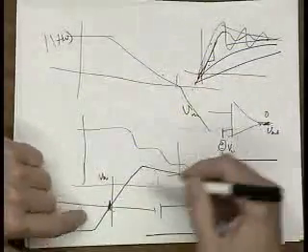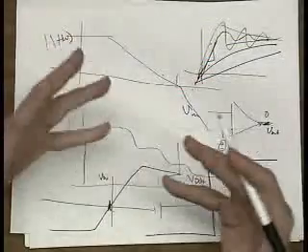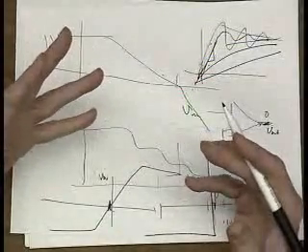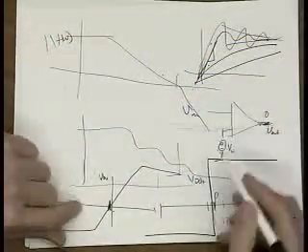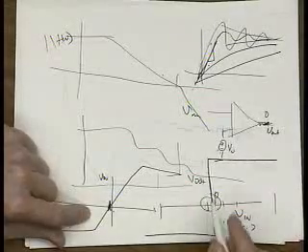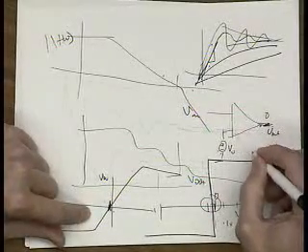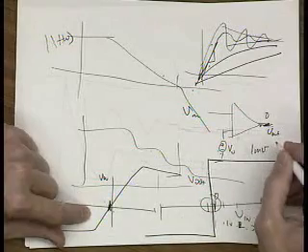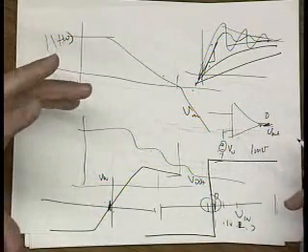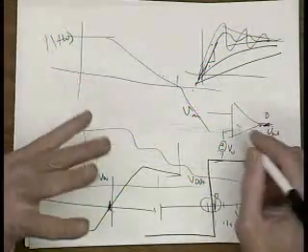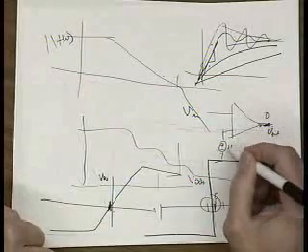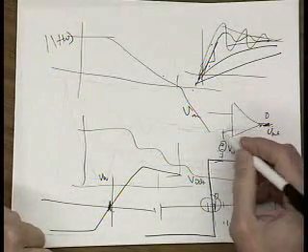Now, if you don't get a curve like this, that means there's no voltage on the input that's going to work. So you've got another problem. But if you see this kind of transition, find out where this is. You're allowed up to a millivolt of offset voltage in your final design. So certainly make use of that when you're doing your analysis.